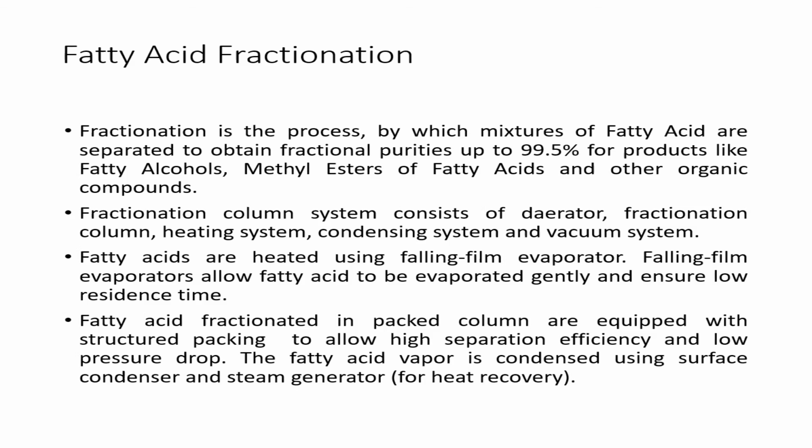Fractionation of fatty alcohols. Fractionation is a process by which mixtures of fatty acids are separated to obtain fractional purities of up to 99.5% for products like fatty alcohols, methyl esters of fatty acids, and other organic compounds. The fractionation column system consists of a deaerator, fractionation column, heating system, condensing system, and vacuum system.